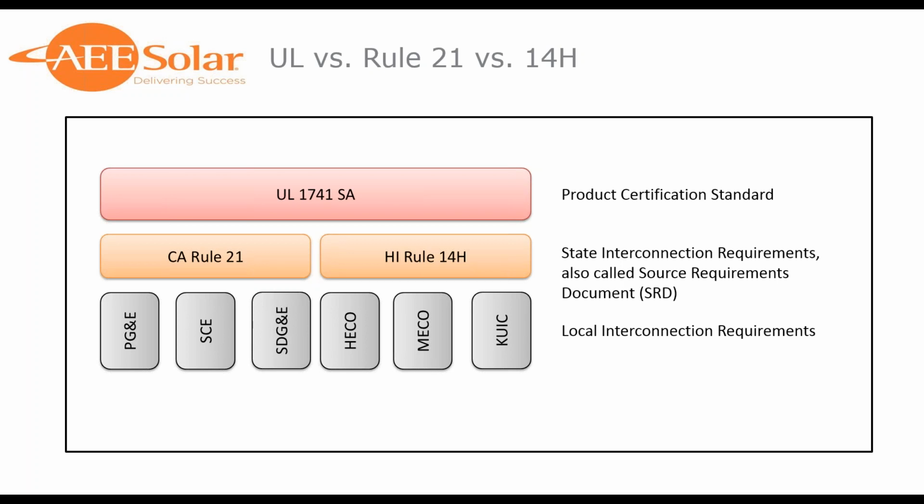We'll see some specific examples of this in a few slides. Finally, this gray layer, and it was not gray intentionally. I realize that's a little tongue-in-cheek, but this gray layer of local interconnection requirements are coming down from the local utility districts. So they can specify local interconnection requirements more precisely, provided it's approved by the regulatory agency. So sometimes this is calling for an additional meter. Sometimes it's additional disconnecting means, etc. In this case that we're going to be looking at today, it's actually set points, timing.